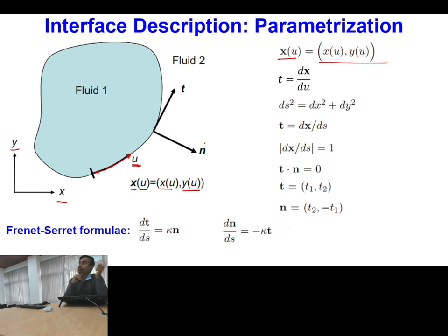So we need to define these. Moreover, if you recall from our earlier knowledge, we have also seen that at the interface some forces also act. Okay, so at the interface we define two types of boundary conditions. One is kinematic boundary conditions and the second is dynamic boundary conditions. In terms of kinematic boundary conditions, we only define the interface velocities parallel and normal to the interface on different sides of the interface, and in the case of the dynamic boundary condition we balance the forces across the interface.